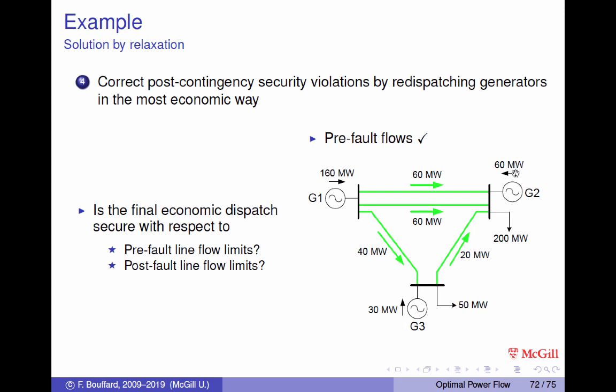Same thing here. So again, here the 200 megawatts is not fully supplied. So we need to have 120, 140 coming to make up for the missing power. And then here at node G3, we'll have the 20 megawatts extra coming from G1, and whatever is left keeps going to node 2.